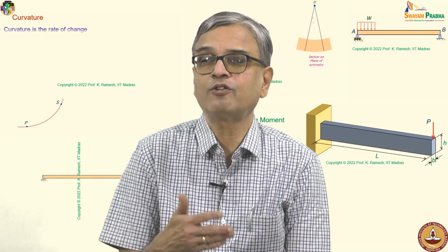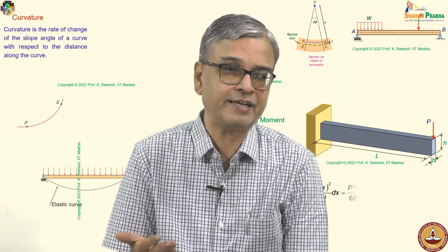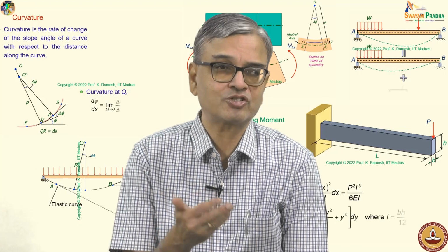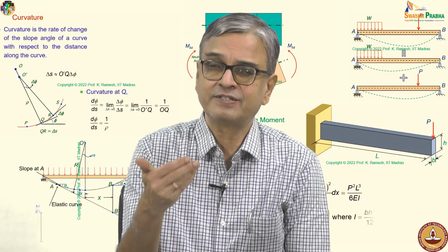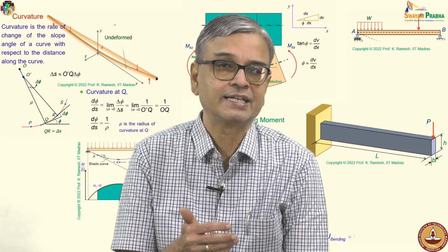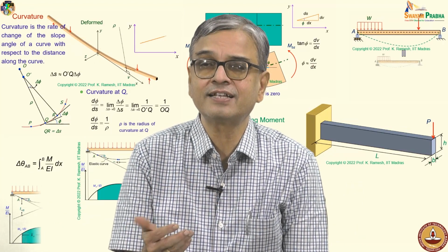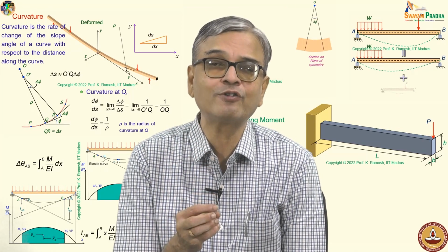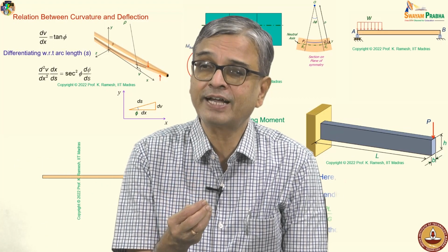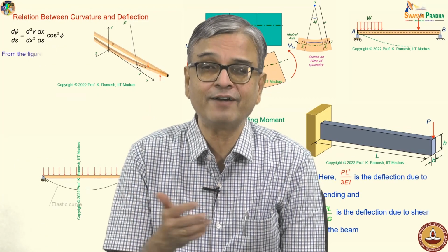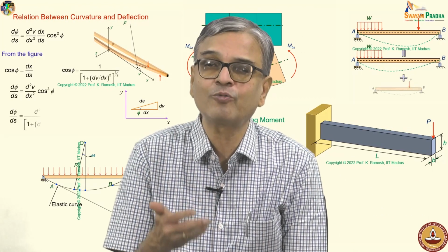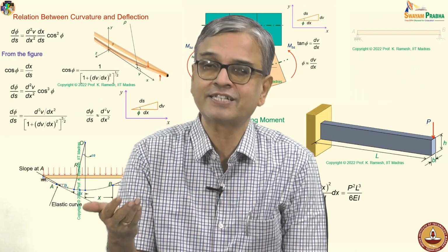So you have to find out, the name itself says moment area. Area is nothing but integration. Okay, that's why instead of doing a mathematical integration, we do it in a graphical sense. And when I go in a graphical sense, only if I am in a position to find out the area, which becomes simpler, the bending moment diagram becomes simpler when I have concentrated load. When I have distributed load, I am going to have second degree curve or third degree curve depending on what kind of load variation I have.